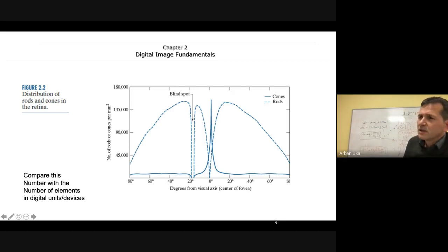In fact, the way to construct a pixel is that we have to determine an area where if a photon is incident on this area, we want that to be separated from the neighboring region on the camera, so that we can have a high spatial resolution. So if we want to detect a hair, we put it under a microscope, so that the light is projected onto different pixels and we can detect the edge of a hair.